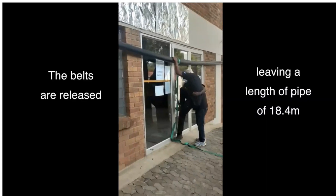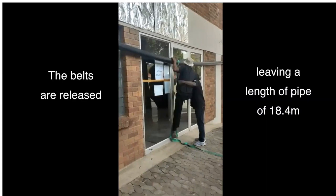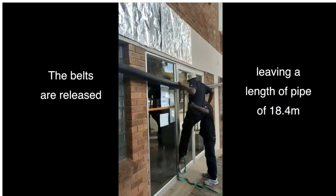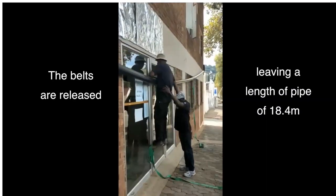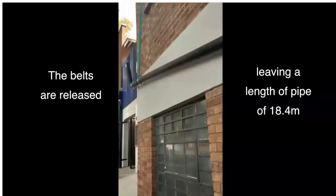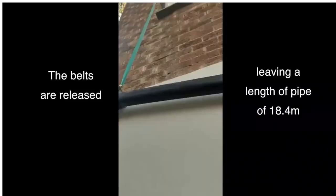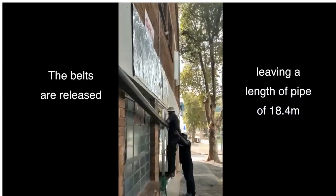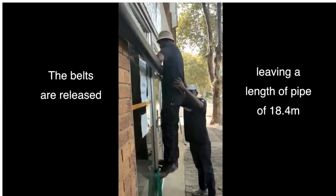At this point, we had a whole lot of guys swinging on the pipe. That's 85 kilograms hanging on the middle. This has left a section of pipe 18.4 meters long without any support in the middle, with the total weight of the water of 176 kilograms plus 85 kilograms of tundra hanging and swinging in the middle.